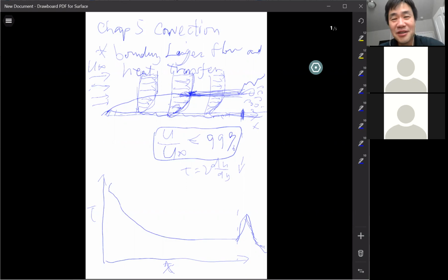Actually, 300 years ago, when the old Scottish played golf, the ball was indeed a smooth ball. The dimple is a new thing, it's not original. But then they noticed that when the ball got very old and very non-smooth, it seemed like they hit the ball further. So they thought, why not make the ball not smooth, with roughness on it? Then with the same strength, I hit the ball further. Actually, that's true.